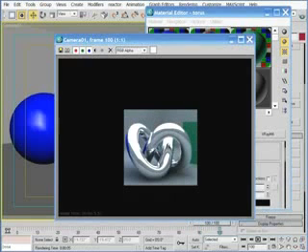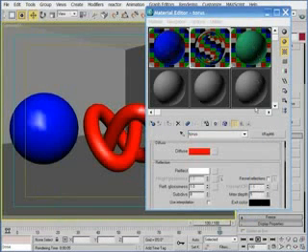Everything looks okay right now, but if you look close, you can see these thin black lines in certain areas. These areas are the areas in which light wanted to bounce more than 5 times, but instead of bouncing more than 5 times, VRay stopped the bouncing and replaced the pixels in question with the exit color that is shown in the exit color swatch, shown here, which by default is set to black.